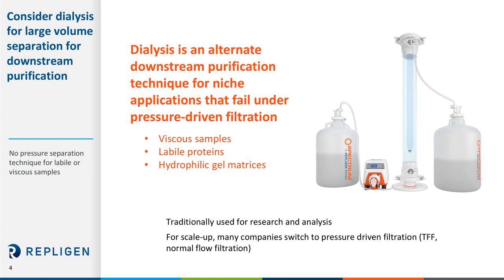So traditionally, dialysis is used at the research analysis scale, and at scale-up, many companies will switch to a pressure-driven technology like tangential flow or normal flow filtration. The crux of this presentation is I want you to consider dialysis as a large volume separation tool for downstream purification. It's specifically good in niche applications that may fail under pressure-driven filtration.